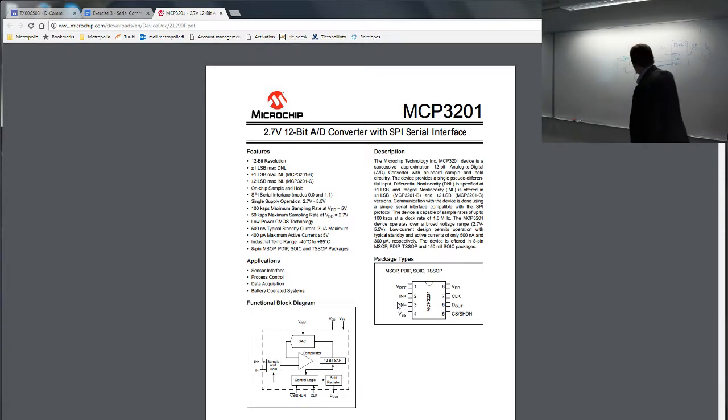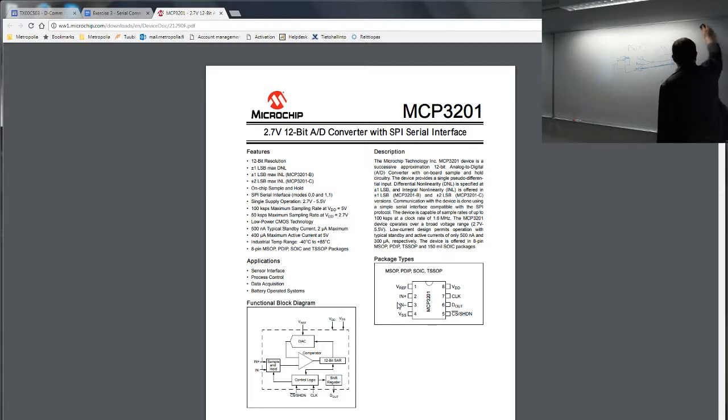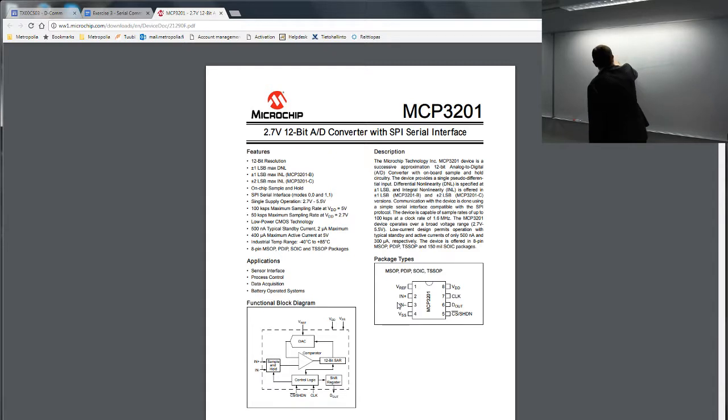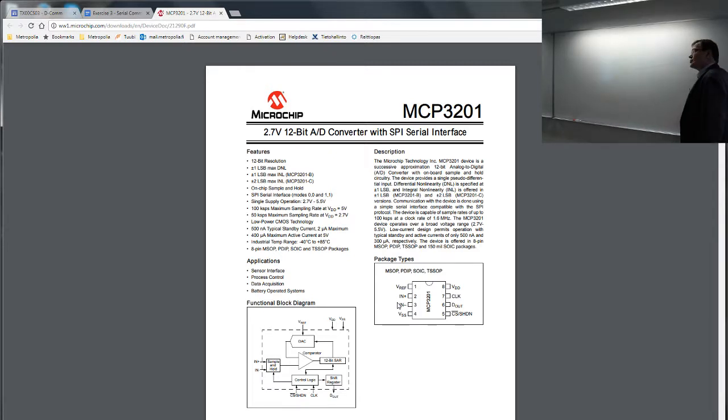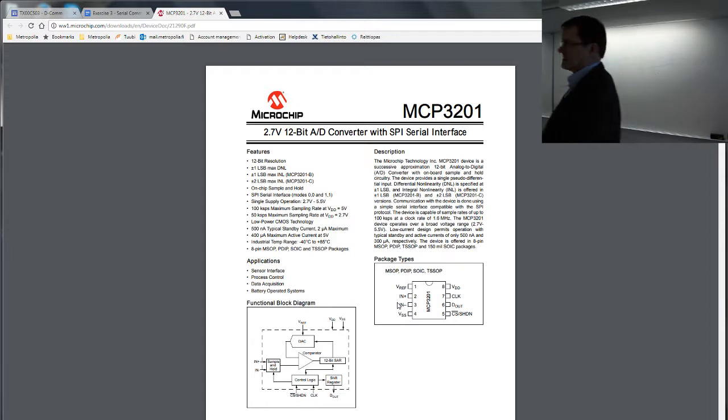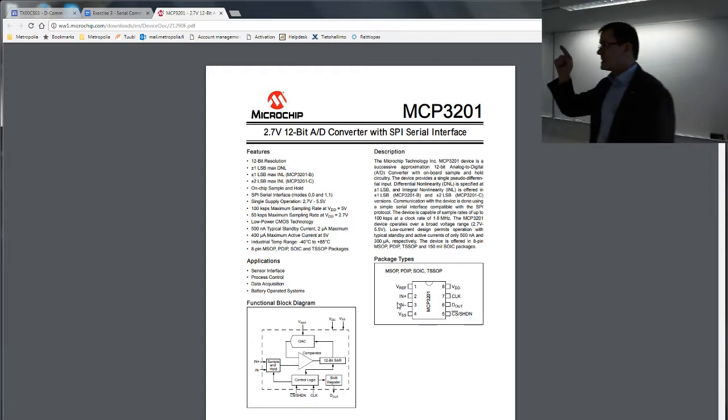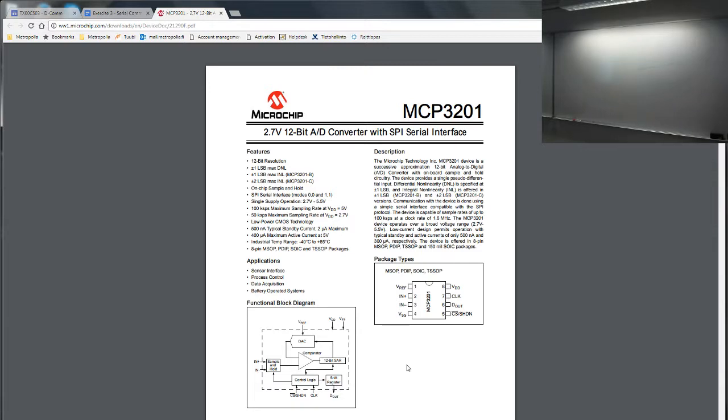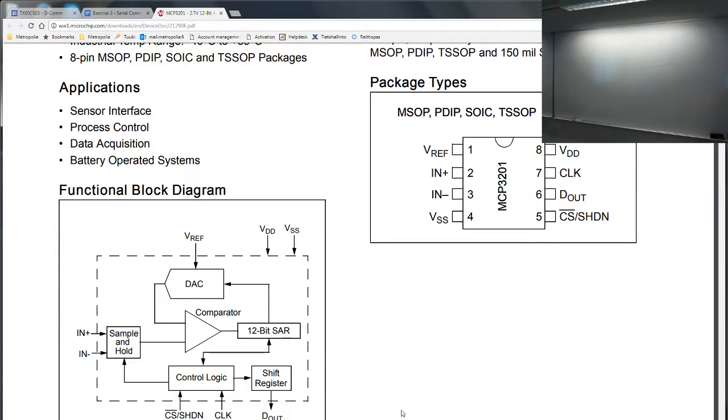Okay, which is the SPI A to D converter. It has 12 true bits. And that's also one excellent place to use a successive approximation register kind of A to D converter, since the whole idea to have it on the SPI bus kind of supports it.